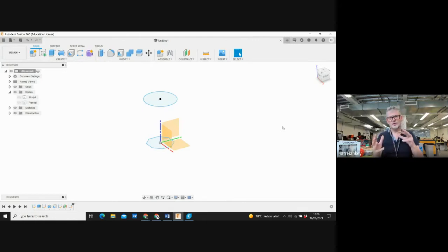I'm just going to hide that origin. Of course, we can do that by going up to the origin on the left-hand side and just left clicking on the eye there. So we can extrude an object up and down. We've got our revolve, which can revolve our plane around. And Owen also showed you the spline, and it was a sweep, I think it was, where we take a shape and sweep along that line. And we could twist it on the way, make it smaller and larger. I'm going to see if I can remember how to do a loft between these two. So I'm going to loft between two planes that I've created to fill the gap between the two.